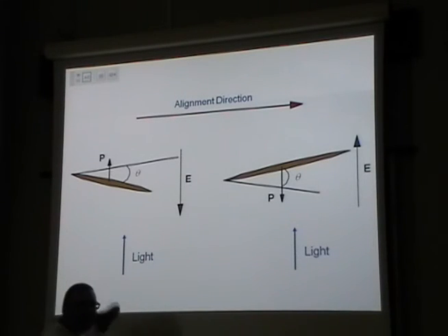However, from the engineering perspective, what do I have here? I have NE and I have N0, and I have the ability now to rotate it, not like a nematic, where my liquid crystal starts like this and goes like that. I now have my liquid crystal starting like this, and it goes like that. So I'm rotating it in the plane of the cell rather than out of the plane, as we saw with the nematic. This is a different electro-optic effect.